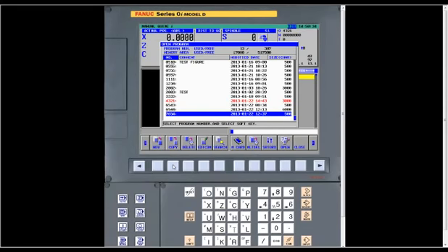Can the G-code output use G70, G71, G72? No, I'm sorry, say that again, Mark. Okay. Can the G-code output use G70, G71, G72? Yes, it can. It will use those cycles.